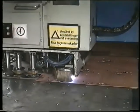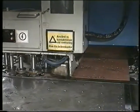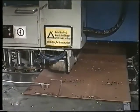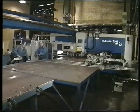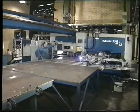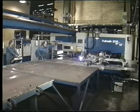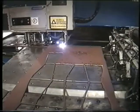Today, cutting is performed with oxygen plasma, whereas earlier air plasma was used. Air plasma prepared joints, however, had a tendency to show signs of porosity in the weld beads. After having switched to oxygen plasma, these defects were eliminated entirely. This is of extreme importance for structures designed to carry a heavy load.